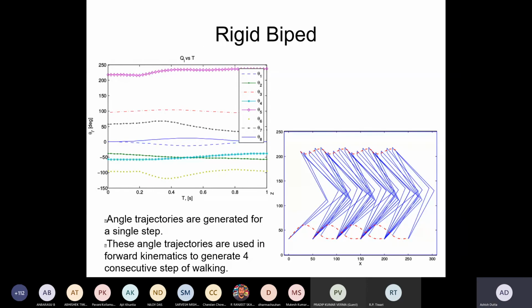Now, doing that, what we did find is you can find the optimal trajectory for a compliant robot also. So this is a compliant robot, which has one of the links flexible, and this is the optimal trajectory. You can see that the trajectory appears to be an S-curve also. So this one also has a human-like trajectory, which is an S-curve.